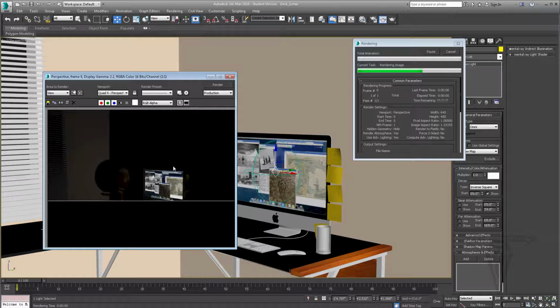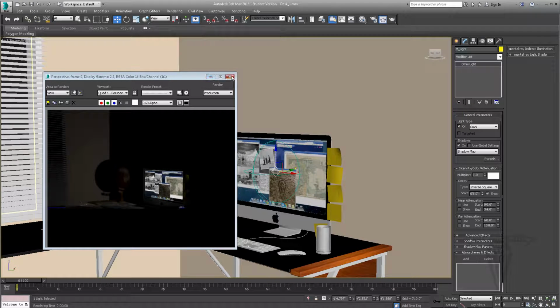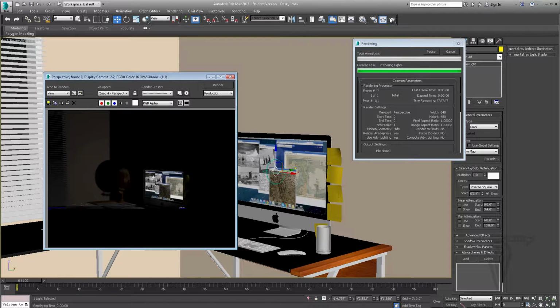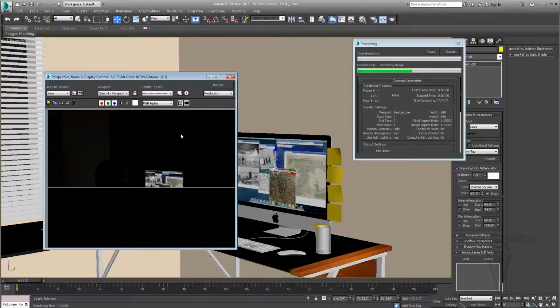And you can see here the scene is a lot dimmer because the light is starting to decay from this point as it goes into the room. All right, so I'm going to hit cancel. That's pretty good. I can dial it up more or even less. Let's say 0.2 and click render. You can see here it's really dark now. The scene is barely being lit, like the back wall, but things that are closer to the light will be lit more. So that's one way of controlling the light in the scene.